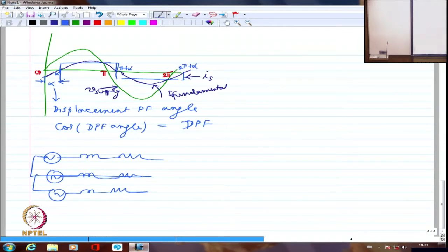So whenever I connect an induction motor or anything which requires a sinusoidal supply, they are all going to get all these harmonic voltages also injected into them, which is not good for the induction machine, because we analyze the induction motor assuming it's all a sinusoidal supply. The moment there is a non-sinusoidal supply, I may have fifth harmonic, seventh harmonic, third harmonic, 11th harmonic. So I will have different revolving magnetic fields.